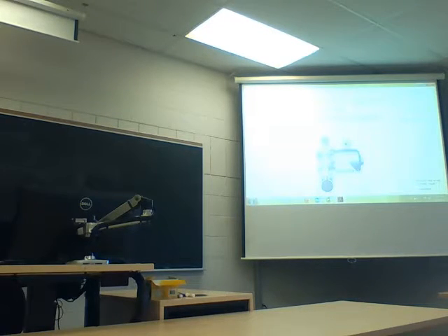Isn't that all three? Yeah, but these ones definitely more so. The other ones could give a medium pressure, up to 1,000 kPa. These ones here are only 350 kPa, which is definitely considered a lower pressure. But volume is amazing in these puppies. You can put out a lot of volume. So they're usually in a place where you want a lot of volume with low pressure. A pretty simple fan compressor.